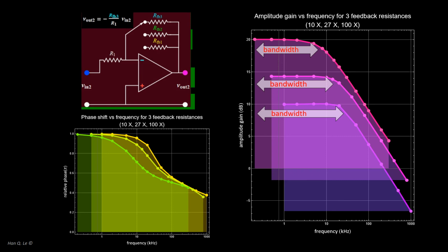But here, imagine, suppose you use this amplifier, set at 14 dB gain, for a drone or robot in your capstone project, to process some sensor signals. If the sensor signal frequency is in, say, few kilohertz range around the white dashed line, the expected signal strength will be approximately indicated by the white dot.